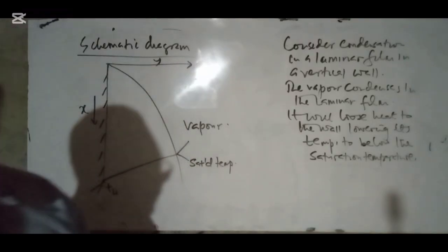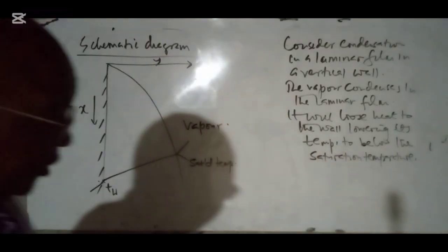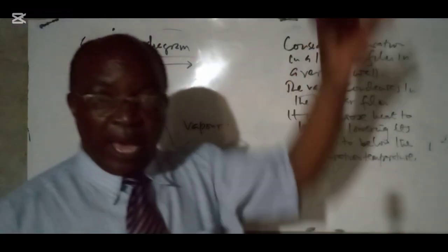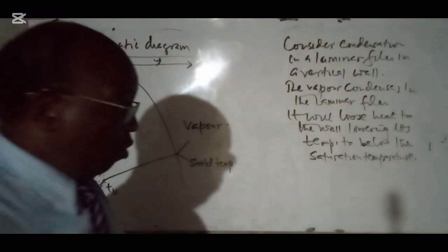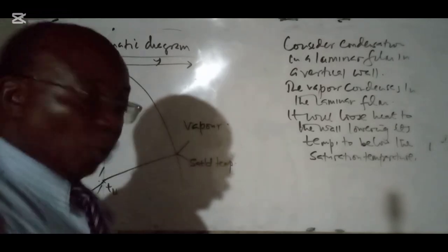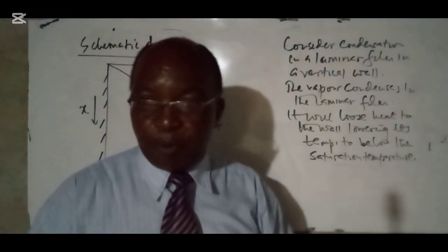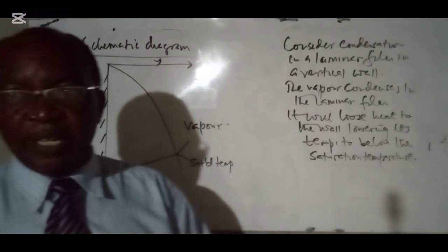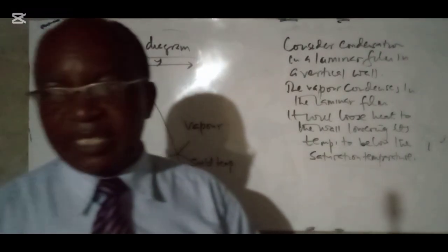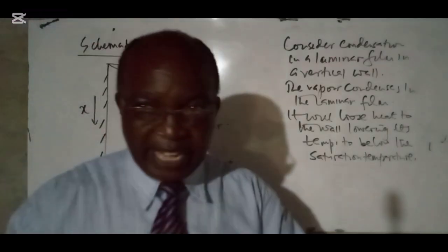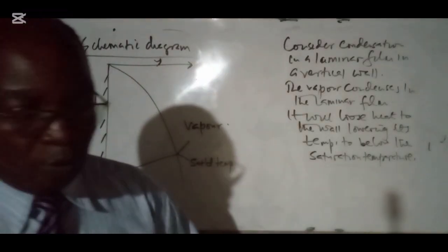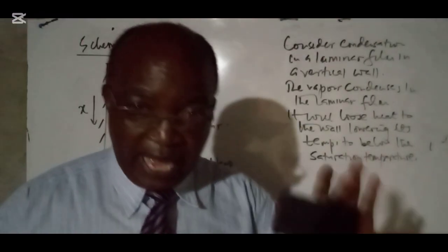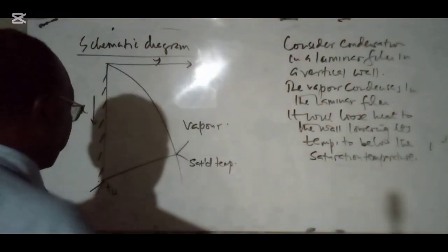And of course, the liquid elements in the system will either move downwards or upwards. In other words, they will move parallel to the vertical wall, and the forces causing these movements are not hydrostatic pressure, as we have seen in other cases, or inertial forces, but rather a complementarity between viscous forces and gravitational forces.